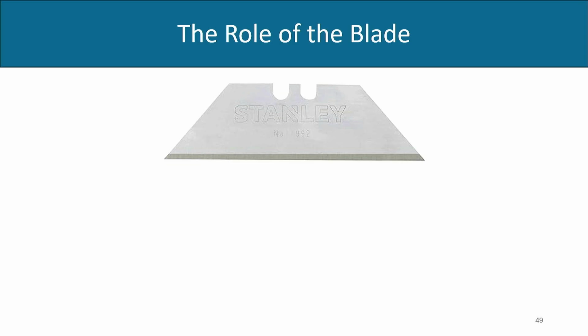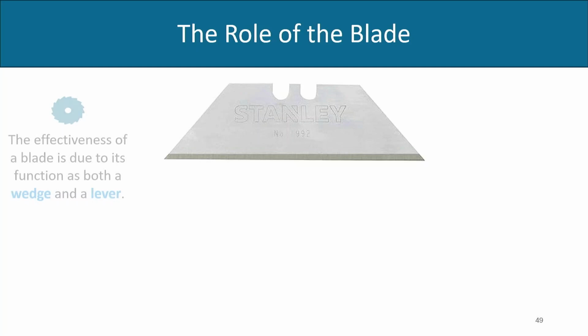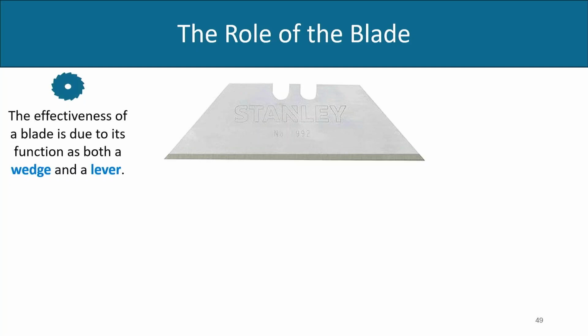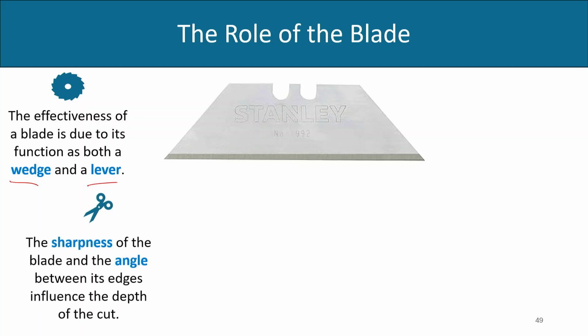The effectiveness of the blade is due to its function as both wedge and lever. So, both wedge and lever functions will be there, and the sharpness of the blade and the angle between the edges influence the depth of the cut.